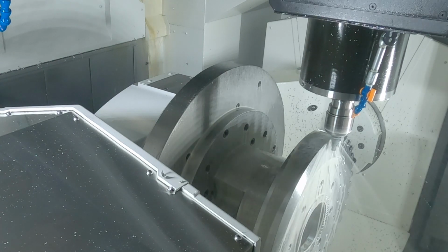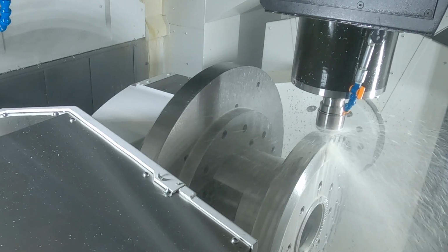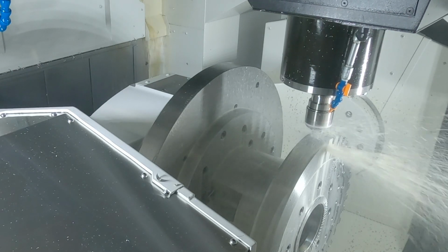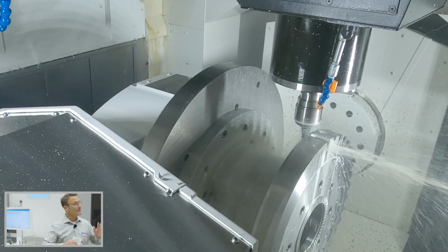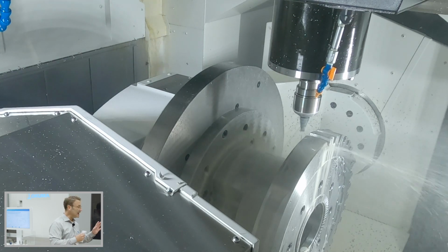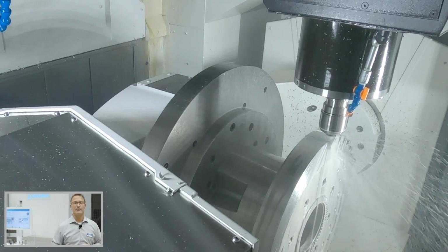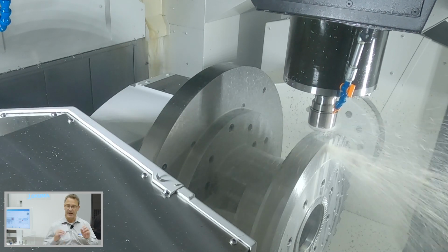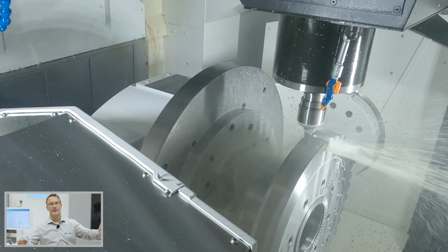When we're coming back to the multitasking machine, also here we have turning, we have milling, we have all kinds of drillings, etc. We also have the functionality of adding the gearbox, the gear package. So we also can have hobbing on this machine, and we also can have skiving, which in the last couple of years is a very outstanding process and really efficient gear machining. We had some testing for a bigger aerospace customer up in the UK, with a diameter of 1 meter, module 5. They were more than surprised about the quality we could have on that machine.